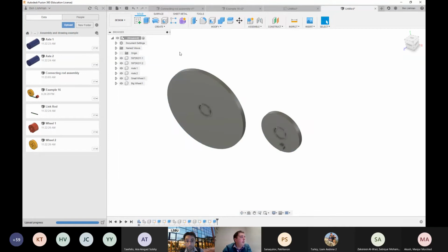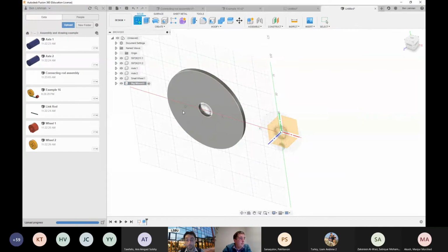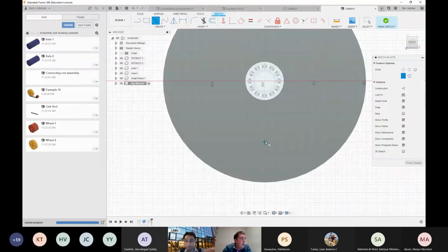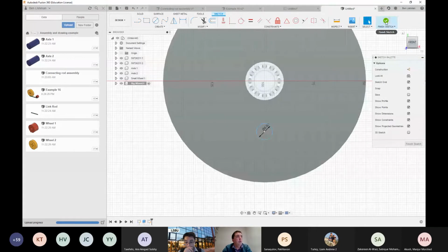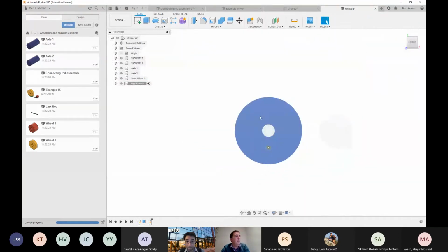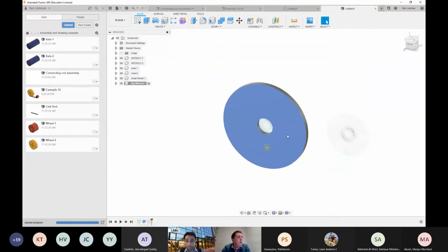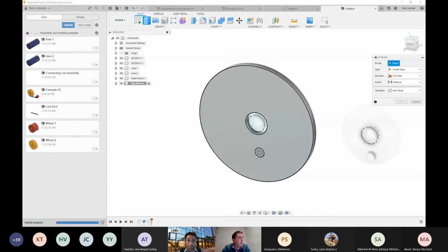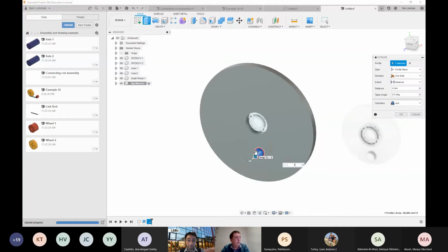Back to the top level of the assembly and just look at things, and now I want the same stub on the big wheel. I'll sketch on the face of it. I'll add in another 8 millimeter diameter circle. I'm reasonably happy with where that sits. Again, I'm doing things by eye here rather than to be absolutely bang on, and I know that I can come back and adjust any dimensions later. Sorry, I clicked sketch, but I meant to click extrude, the same 4 millimeters as before.